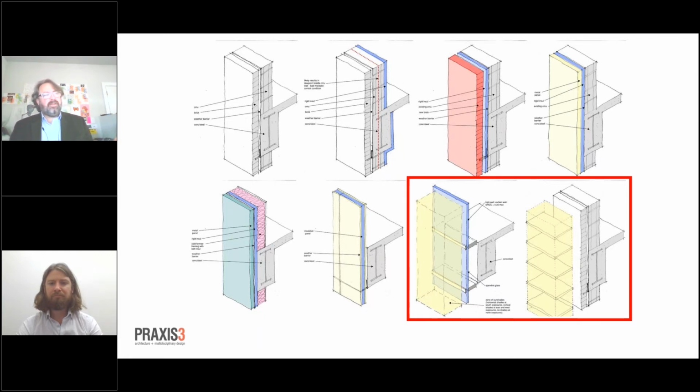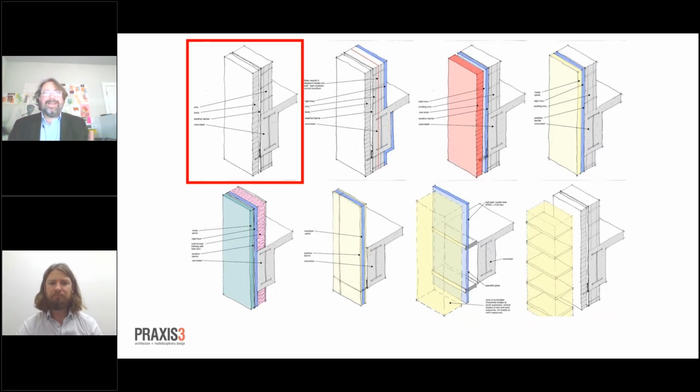And we ultimately, you'll not be surprised to find out, ended up keeping the existing wall, because the wall had been working pretty well for about 50 years. And in looking at the energy model, what we discovered was that most of the performance benefits that we got on this project, and they're pretty substantial, we'll look at those later, happened by how we treated the openings. And the needle wasn't moved very much by any of the things that we did to the solid envelope. It would improve this way or that, but when you compared that against all the embodied carbon that was in these existing walls and how well they were already performing, and that we could get increased performance by improving the glazing systems, we would stick with the existing wall.